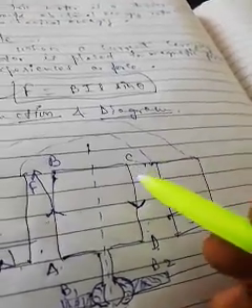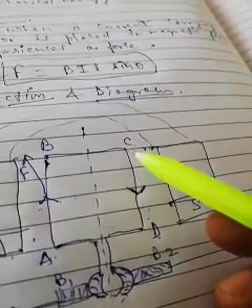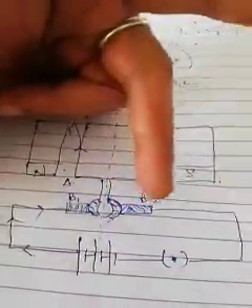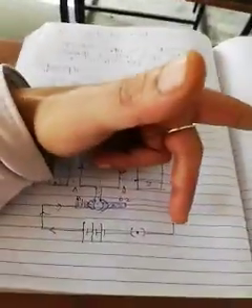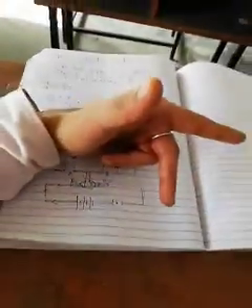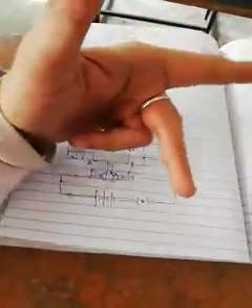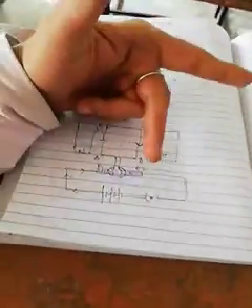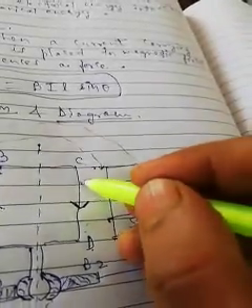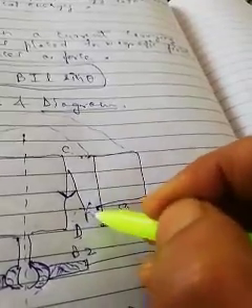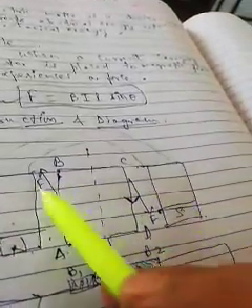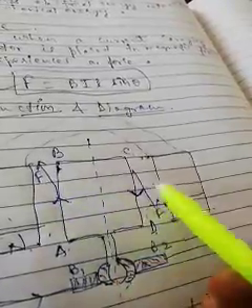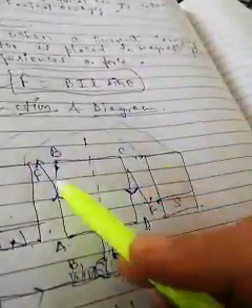Similarly, we apply Fleming's left-hand rule to decide the direction of force on side CD. You can see the thumb points in the upward direction, with the magnetic field north to south and the current in the appropriate direction. These two forces, equal and opposite, rotate the coil.